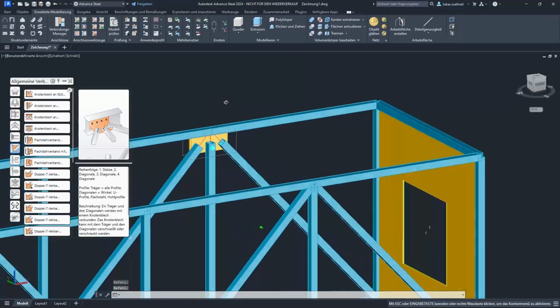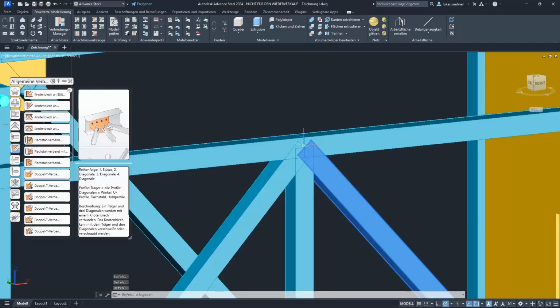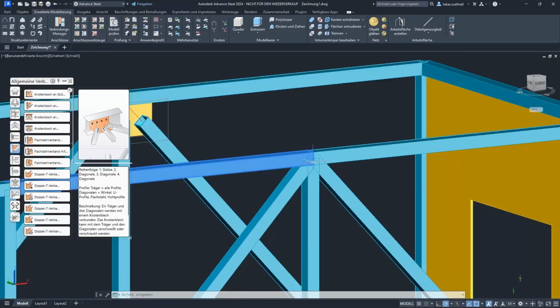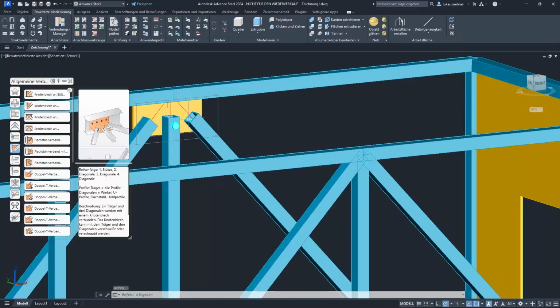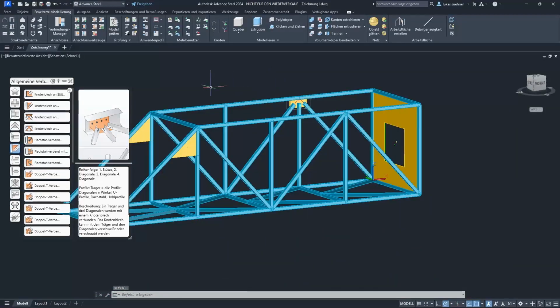So it's clearly visible, even though we exported based on the center lines of the beams, which we can see here. That is not an issue in Advanced Steel. It doesn't matter. It will cut or shorten the members according to, for example, the steel joint that we define in here. So it's definitely usable. Okay, so far regarding the SDNF format.